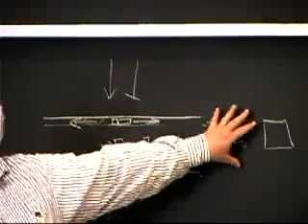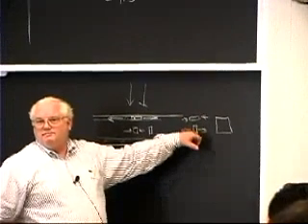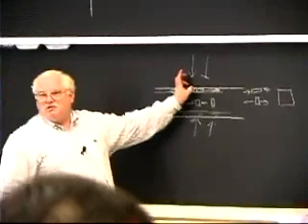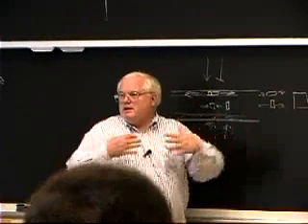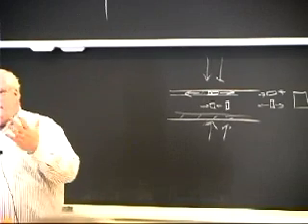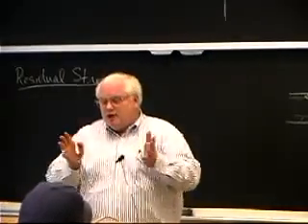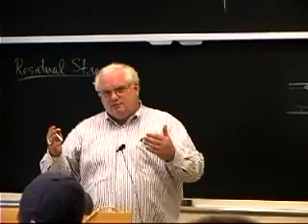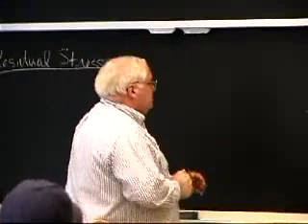So the residual stresses are compressive on the surface when it's cooled down and tensile in the center. Whereas when it's cooling, it's exactly the opposite. What happens is I yield the material here and change its shape, but when it's all said and done, they never really change their shape except on a microscopic scale, and they're all bound together, and I'll have residual stresses. And the easiest thing for me to always remember, and I've gone through and analyzed a number of them, and it's never failed: whatever the stress state is when it's hot, you will have the exact opposite stress state when it's cold. Okay?